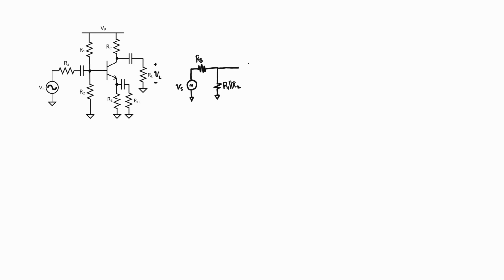We now enter our transistor, and I'm going to replace the transistor with a mathematical model. The model works like this. If current I sub B enters the base of a transistor, then the transistor acts to amplify that current by some value, beta, and send it down the collector. The transistor contains a small resistance between the emitter and the base called little r sub e. This is basically the circuit model that I'll be using here.